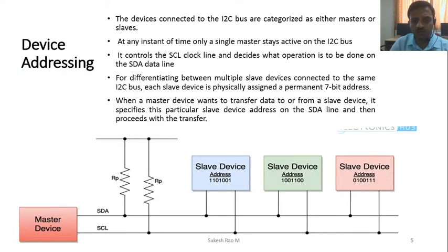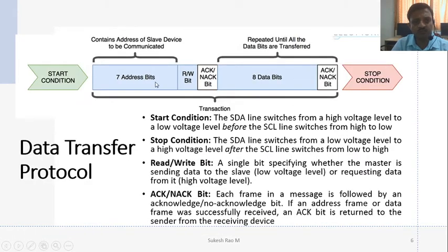Generally these I2C devices are not a single register; they have multiple registers, and each register has a particular address. So whenever you are configuring a certain device, after the start condition, along with the 7-bit address, one more bit goes, which is the read or write bit. Usually read is 1 and write is 0. You need to check the particular data sheet, as it depends. Usually read will be 1, write will be 0. We say write bar and read.